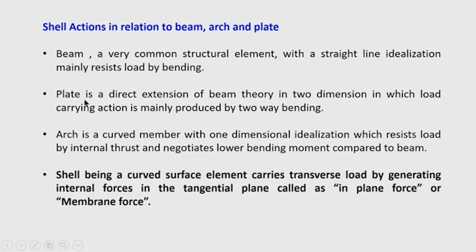So, the plate acts by producing the moment of resistance in the two directions. Now, in the case of a shell, because it is a thin structural element, the loads are mainly resisted by membrane action, that is, in-plane forces are generated and resisted.